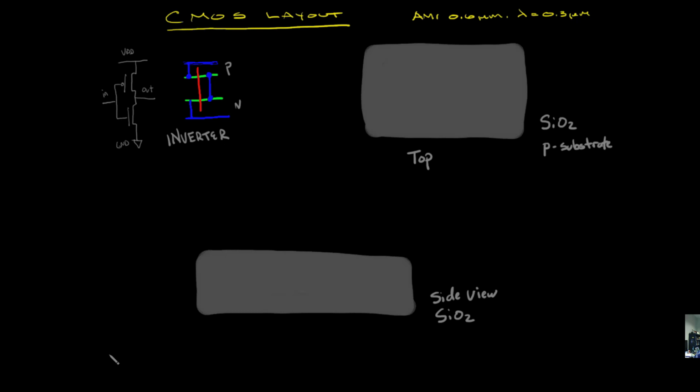The first rule of thumb, of course, is we have to know our lambda. When we go into Virtuoso, this is going to be used to define the sizes of shapes and the distances between things, and I find it handy to keep a list of what those rules are, and maybe even what the ideal sizes of everything are going to be.